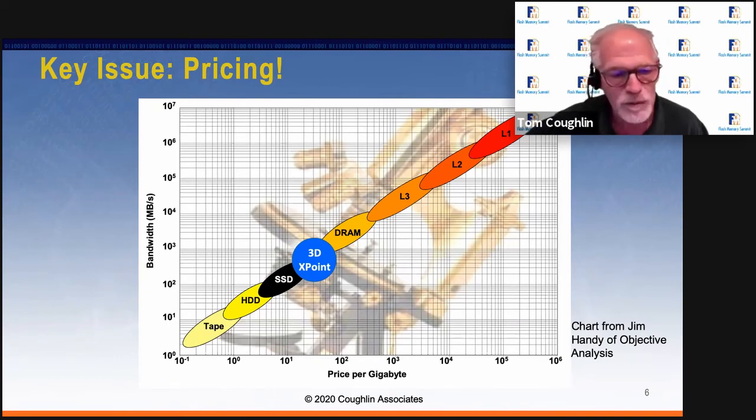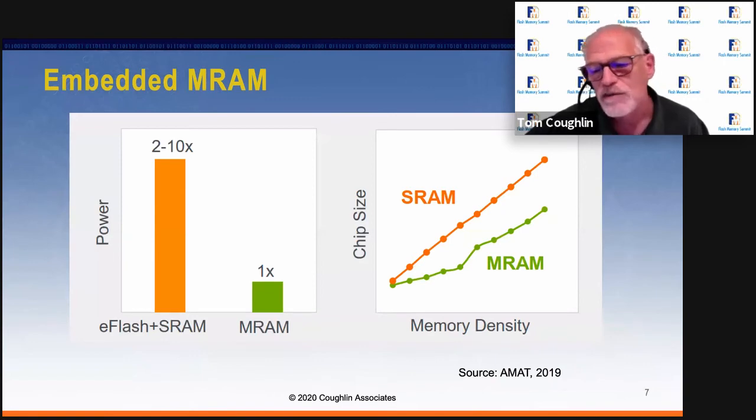I'm going to talk to you a bit more about MRAM. MRAM saves power while reducing a chip's size and cost. We're showing here a comparison with SRAM. Embedded MRAM will shrink smaller than SRAM, as well as NOR flash. A 1T, 2T MRAM bit cell is smaller than a standard 6T SRAM bit cell. And NOR flash hits scaling limits after 28 nanometers, as we said.